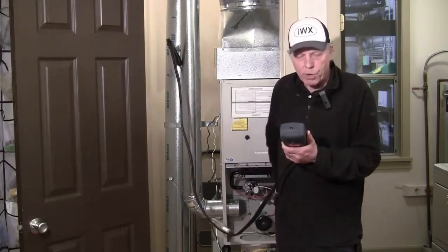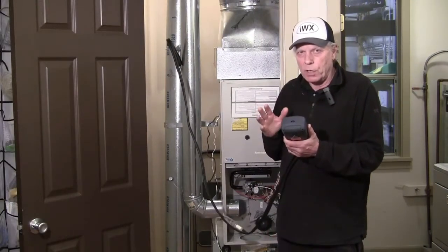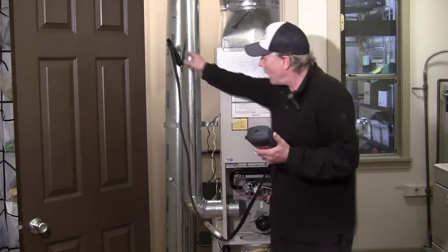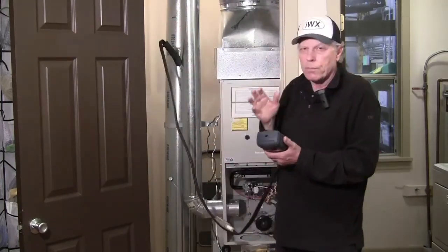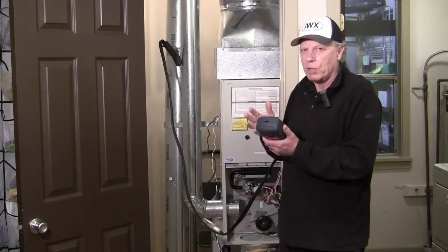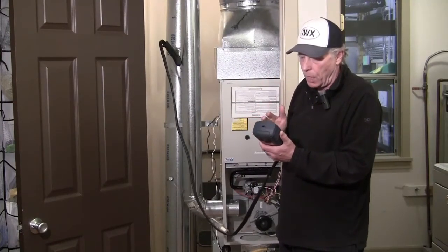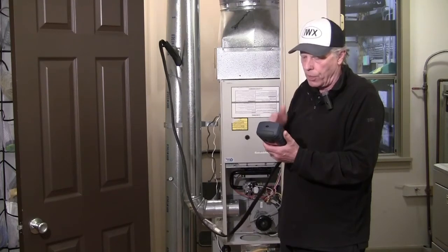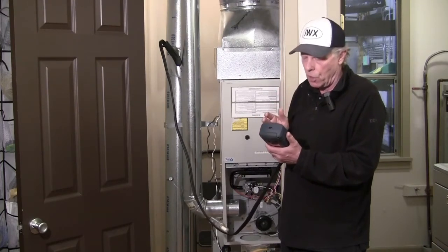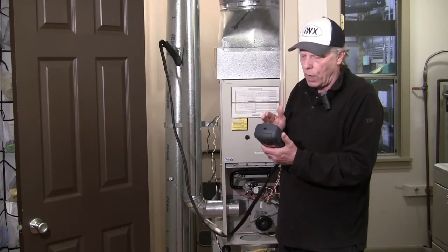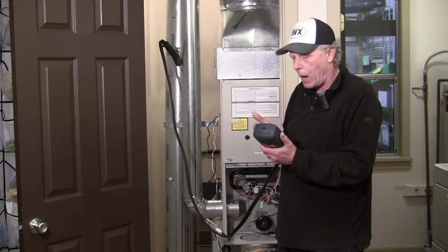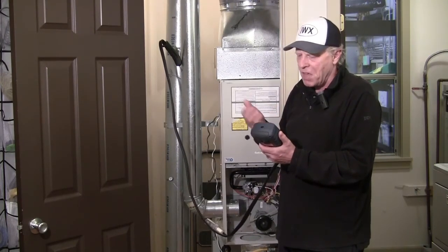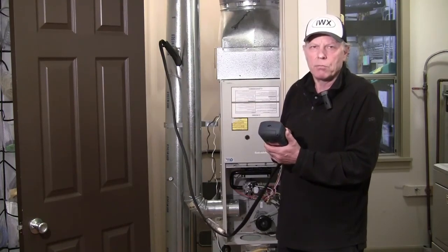I'm on line 3 here, and I'm measuring the CO in the flue gases. I have a hole in the flue here. The furnace has been running for 5 minutes plus, and I'm in the neighborhood of 180 parts per million of CO. Also, I'm looking at the efficiency, and we're at approximately 88% efficiency.